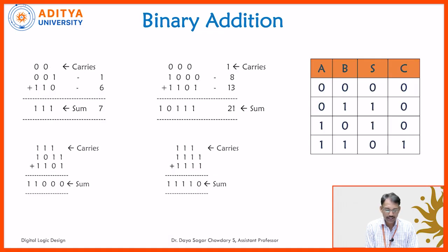Now the same thing: 1 plus 6, we know in decimal, is 7. In binary, 001 is the representation for 1, 110 is the representation for 6, and we can add them to get 111, that is 7. So this is an easy calculation. Observing the 4-bit representation again, the two inputs are 4-bit, but the result is a 5-bit representation.